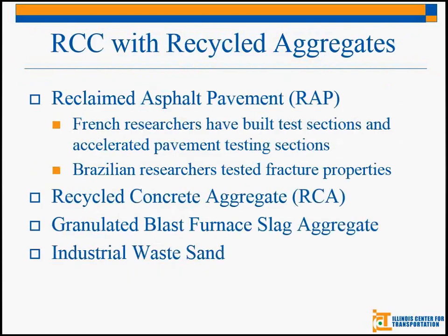All right, so moving on to RCC with recycled aggregates. There has been a fair amount of work with this. People have looked at using recycled asphalt pavements as well as recycled concrete aggregate. There have also been, I think, one or two studies on slag aggregate and industrial waste sand.